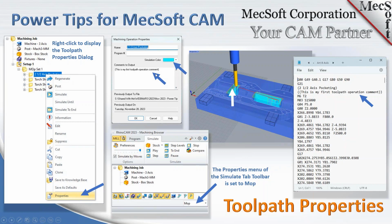If you want to output comments anytime that operation is posted to your G-code, let's say you want some operator notes on a particular operation, you can put those notes in here within brackets or parentheses, and it'll output that. I'll show you how to do that. And then you can also assign a color. This is important if you've got a lot of different tool paths and you want to distinguish one simulation path from another. You can assign each operation a specific color.